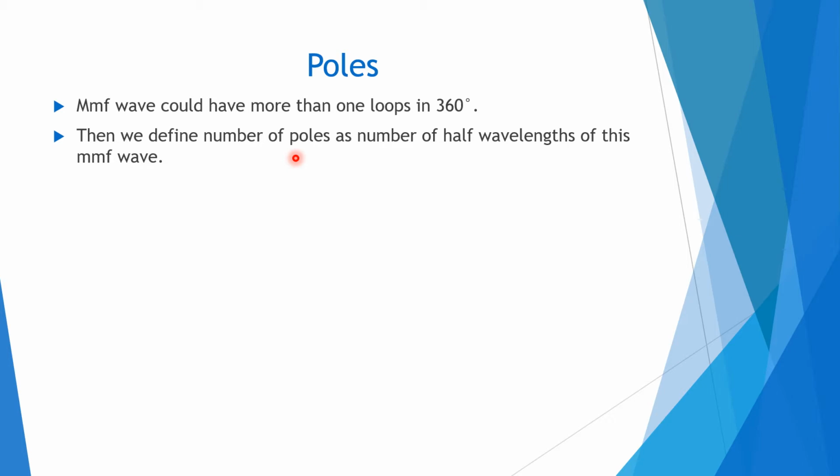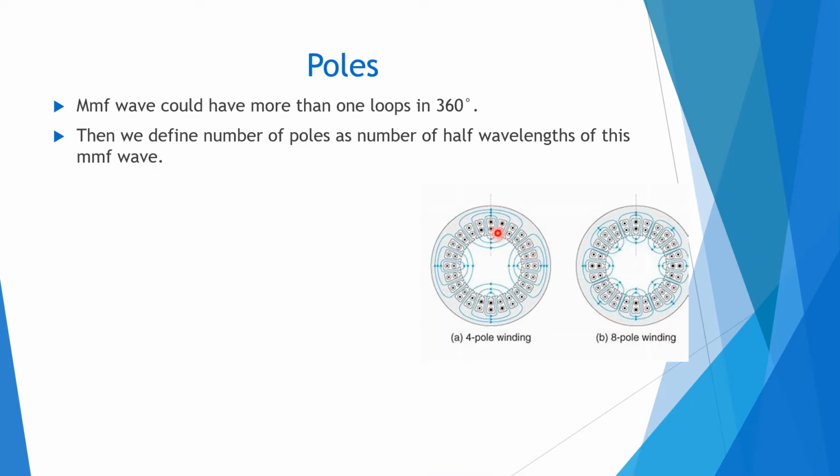windings that you will require to produce that MMF wave. Because to produce that two pole MMF wave, you needed two windings. One was making all the current flow in one direction, and one was making all the MMF flow in the other direction. Then you saw that one of those components cancelled, one of them got added. So that's why we could see that there was a net MMF wave traveling. So if you have more than two poles, you are going to need more than two windings. Now suppose you have a 4-pole motor, right? In this 4-pole stator winding, you can see that there are actually 4 sets of windings, 2 that go in and 2 that come out of the plane. These produce magnetic fields that look like this.